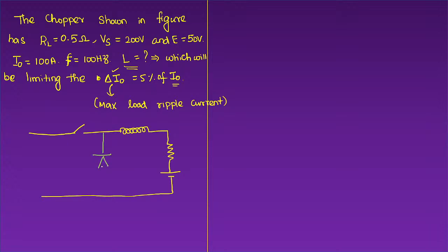You know, it is as usual a buck converter only. There is no big change still. So this is the battery. This is the inductance L, and this is the buck converter. See, they are trying to measure the output voltage across this. They are treating this whole part as a load. So now they are trying to measure the voltage across this. You know, the inductor will basically behave as a short circuit, so it is very easy to calculate.